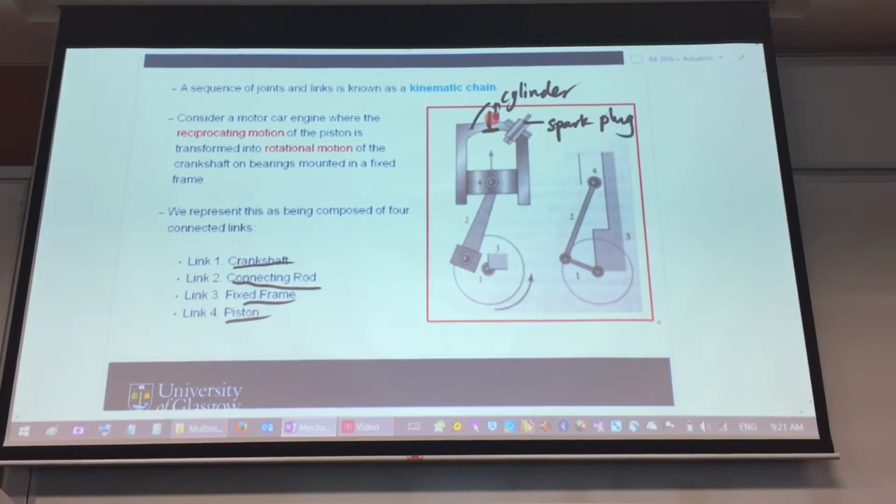It's actually not here. Your valve is actually spring loaded, and you have another shaft over here. That shaft will be profiled in certain patterns so that, as it rotates, it's going to push your valve in and out at certain very precise timing.